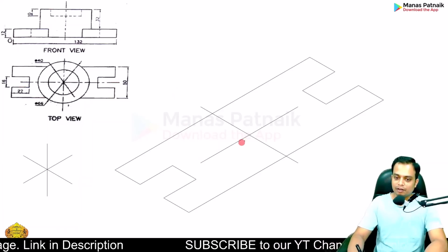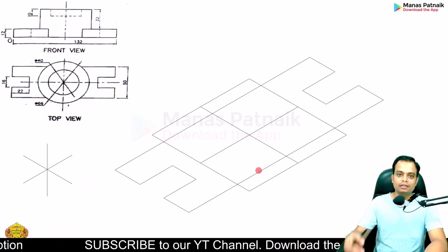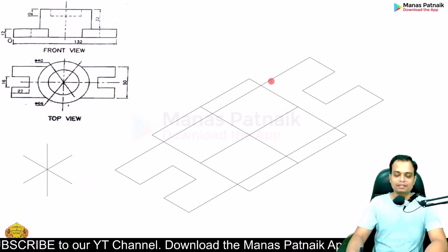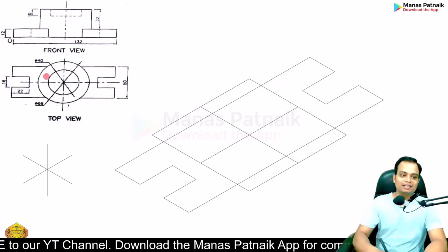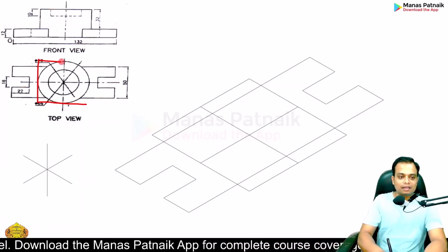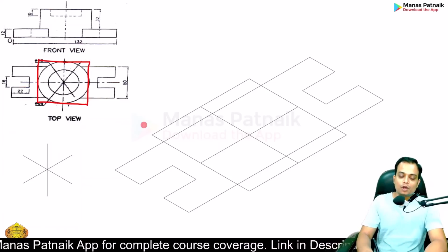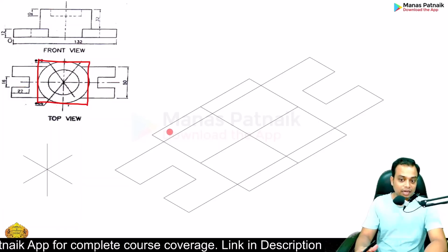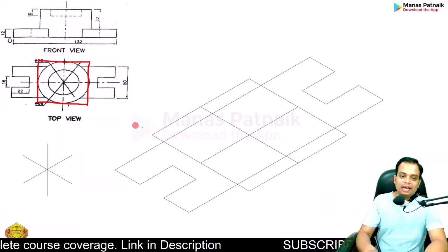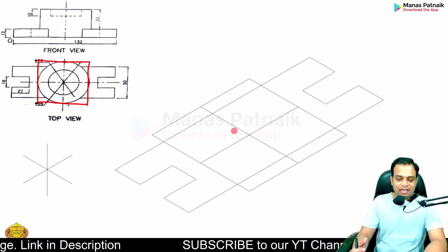Keep your drafter along this line. Make this line and this line. Similarly, these two parallel lines. So it will be enclosed inside this rhombus. In fact, if I can just show you, a square. The isometric view of a square is a rhombus. That is what we've just made. And inside the square, there is a circle. And you know very well that the isometric view of a circle looks like an ellipse, right? And that is what we'll be making.